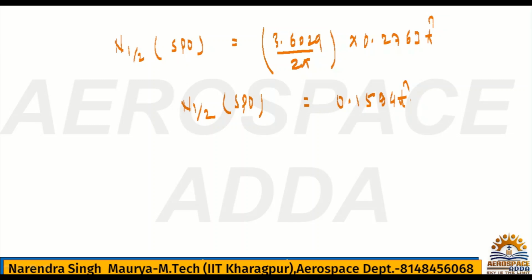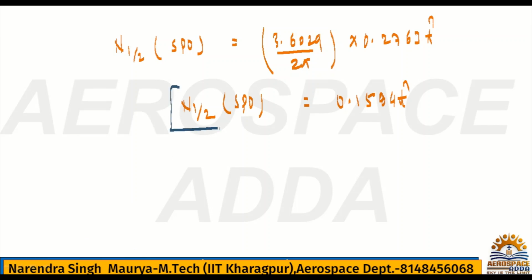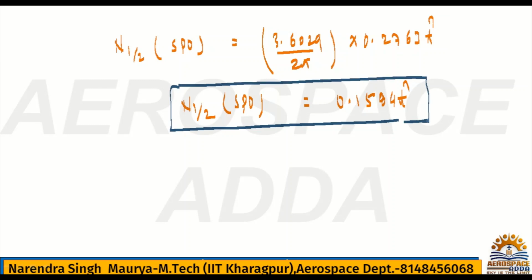Once the details of the airplane are given, like mass, density, velocity and all those things, then T cap also you can write the value, but it is not given, so you can keep this in the same function. All right, this is done. All three values you have calculated: time period, time to half, and number of cycles to half. But this is for the short period oscillation. The same thing you have to perform for the long period oscillation.